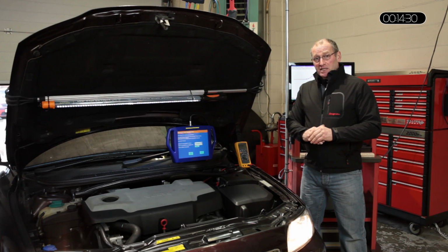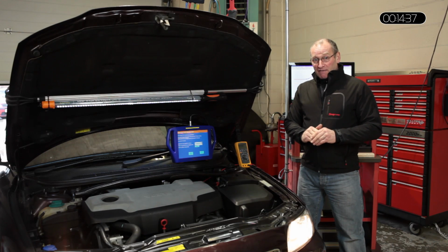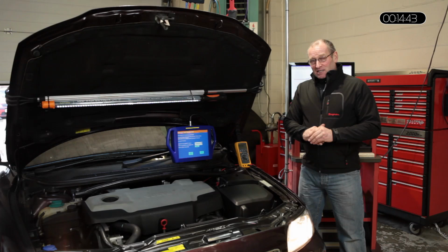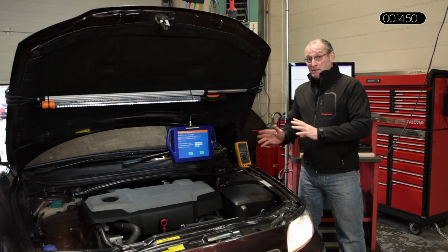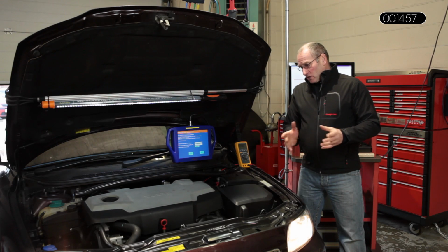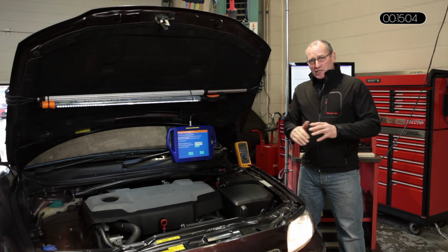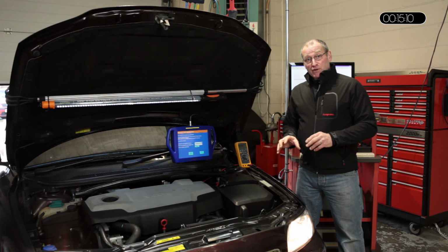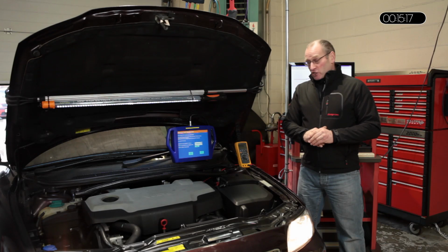I am also aware of the fact that many manufacturers now have removed from their software platform the ability to manually regenerate DPFs. The main reason being, various people have managed to set the vehicle on fire. That, I think, is negligence rather than a software issue. I think they should leave the experienced technicians to do the job and leave the manual DPF regen as a feature, so that we can best decide ourselves if that is a viable procedure to go through. So there are some dangers of force regeneration. I appreciate that, but like everything, with the right preparation, the right process, I see no dangers in this at all. But as I say, some manufacturers have removed forced regeneration.